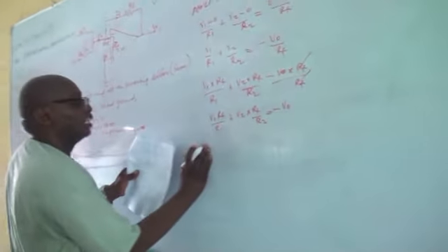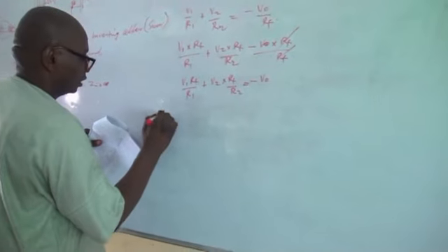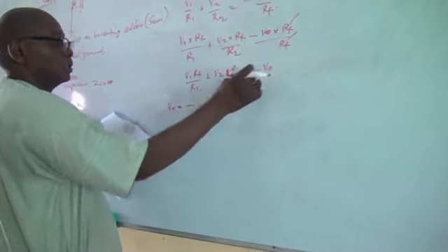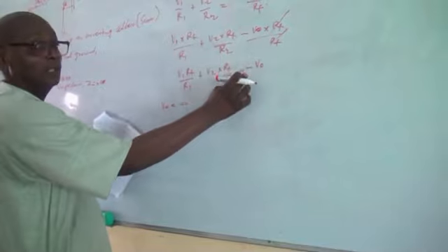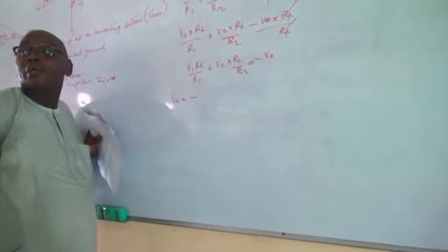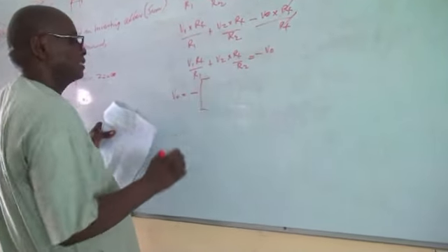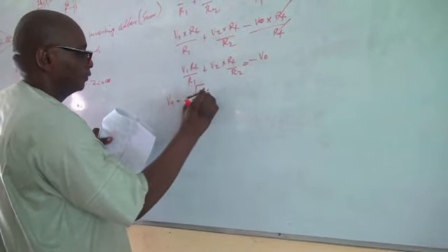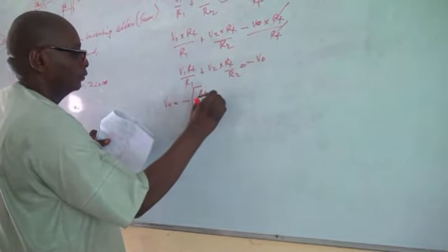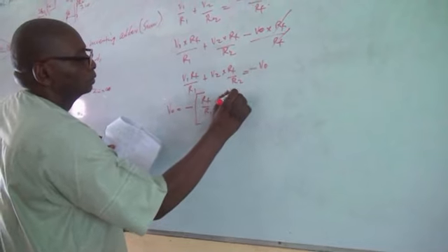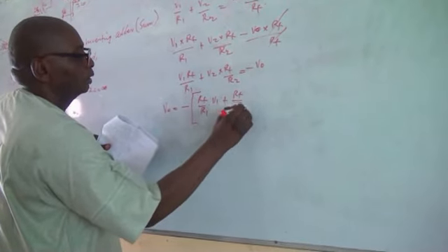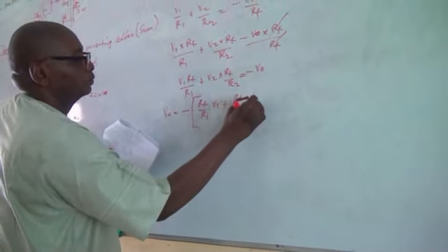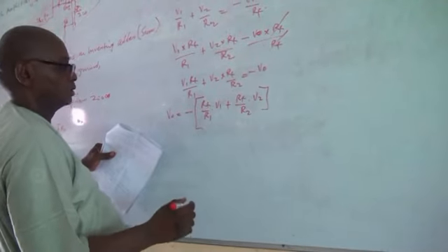When that is done, there is something very important. We have to put aside the voltage gains of this equation. This gives you V0 equals minus, because this is an inverted output already with a minus sign indicating here. Then you put the braces: RF all over R1 times V1 plus RF all over R2 times V2. This is it.